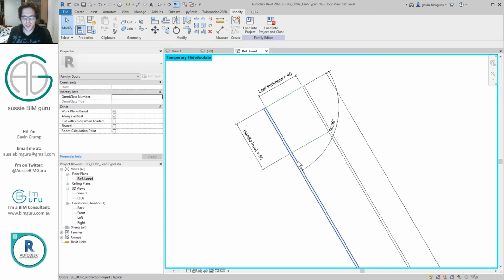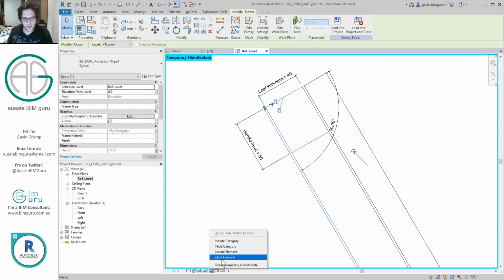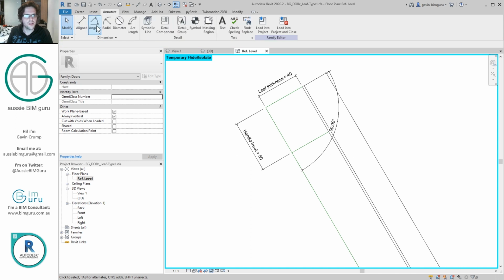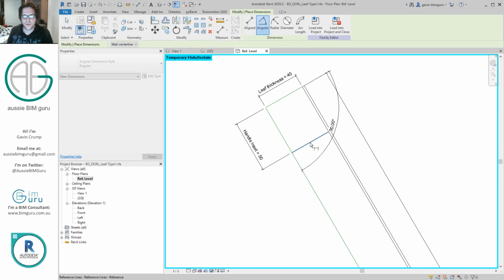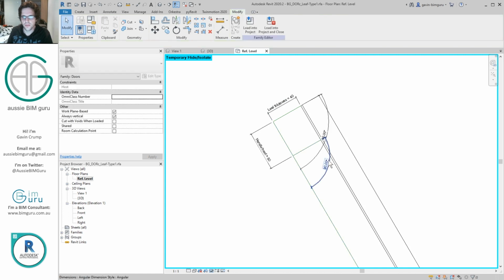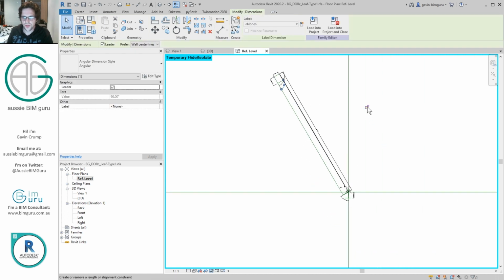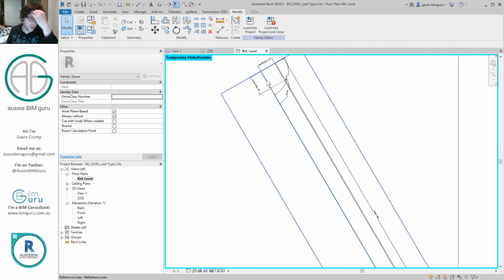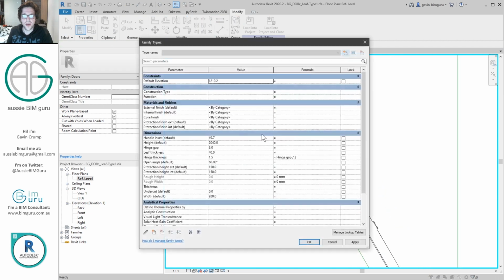What I'm also going to try and do is set up a 90-degree constraint between this new reference line and the current one, so the face of the door. And this should hopefully work. If it does, we should be able to set this to any angle. So we're just going to test this, and it may break. I have found that sometimes when you get to the reflex angles again, it breaks. Oh, wow, okay, it worked the first time.